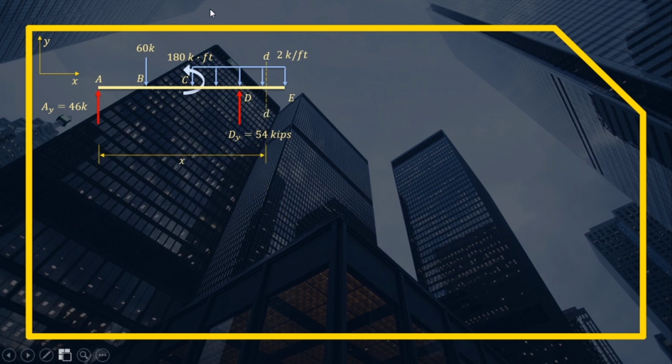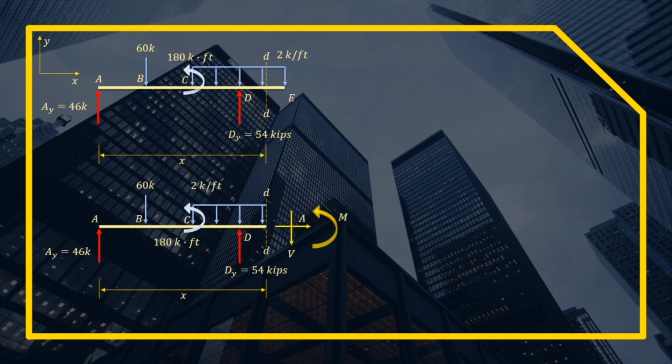So next section, syempre magkakaroon tayo sa pinaka-last na segment, which is DE. So this is the length now for x. And kunin ulit natin yung segment. So ganun pa din yung this segment from the left end. And ganun pa din, magagamit tayo ng equation of equilibrium. So, summation of forces vertical ulit. And equate natin lahat ng pataas sa lahat ng pababa. So, this time, yung pataas, meron tayong dalawa, which is 46 kips and 54 kips. Or, that is AY and DY.